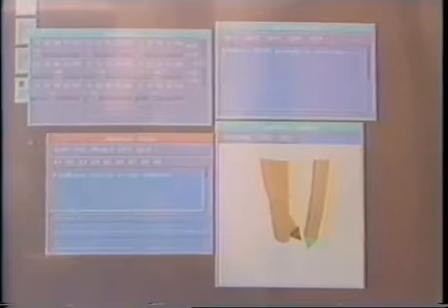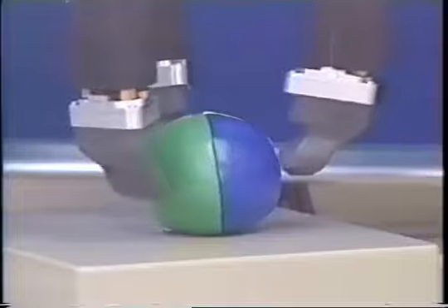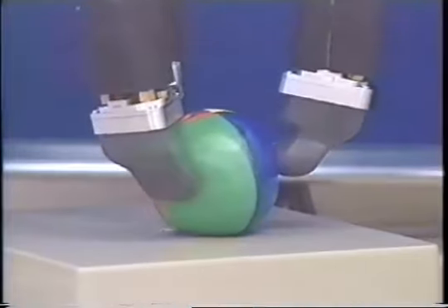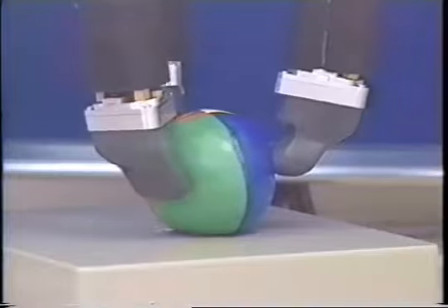To operate the system, a Windows-based graphical user interface is employed. Windows can be dynamically opened and sized to show the current gripper configuration, the contact forces for each finger, the pressure commands to each valve, and to command teleoperation or blind grasping actions. The first Amadeus prototype is now complete, and we are currently developing a second for deployment on a robot arm and for evaluation by scientific and offshore users.